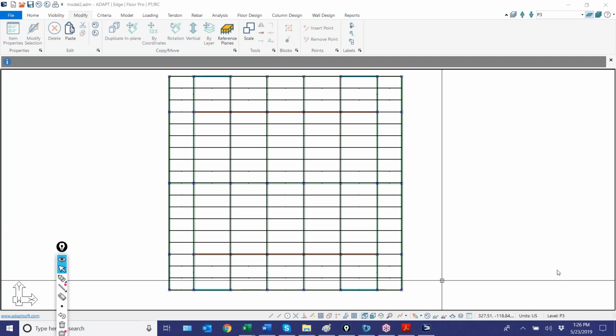Miriam, your question: in Class C, should we change stiffness modifiers, or does the crack deflection take this into consideration? The crack deflection check only applies to horizontal elements like beams and slabs, and it's a post process. So you could run the model first, given your current condition, run crack deflection, determine the level of cracking, and then go back and apply modifiers to the beams and the slab for that level of cracking.